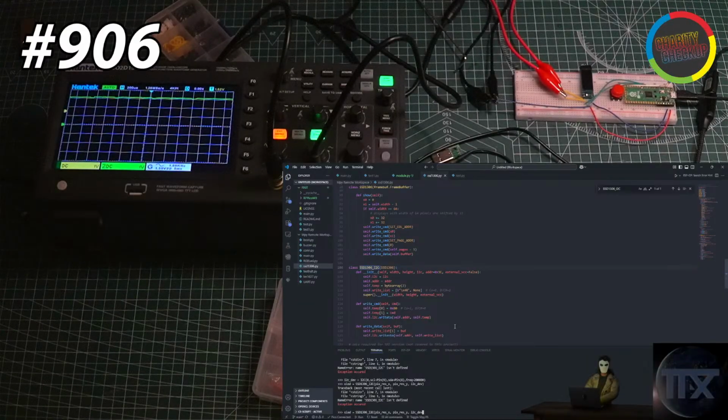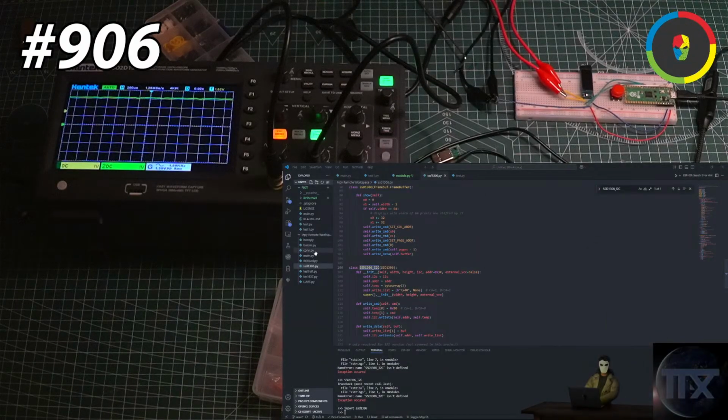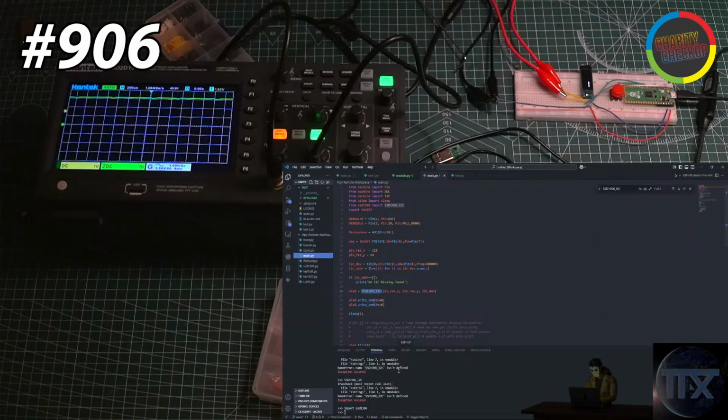The specific reason I set all of this up was so that I wouldn't have to deal with it when the time comes. Okay, import SSD1306. That should import this precise file right here, inside of which the SSD1306 I2C connection is defined. Worst case scenario, we can just do I2C ourselves, manually. I don't know what the manual commands for I2C are exactly. Oh, right, I2C.scan. If you have a variable that already has the pins for I2C defined, just do that variable dot scan with the open and close brackets. Yep, it did. It shows address 60.